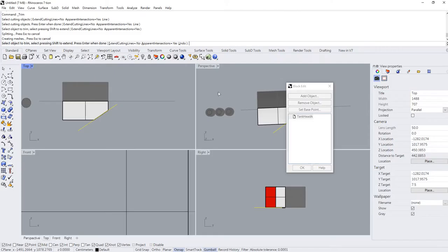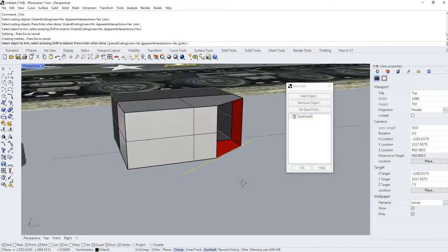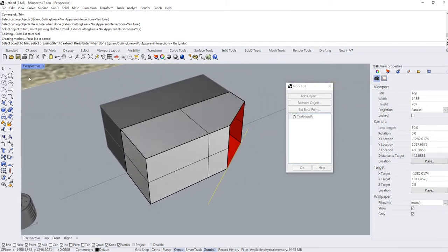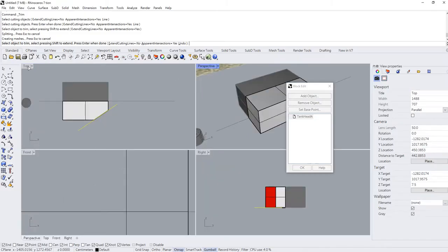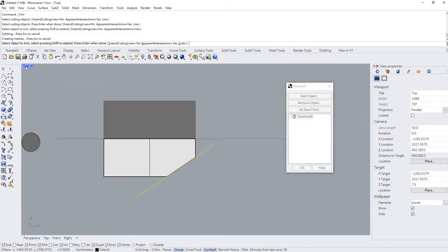If we go to perspective view and you want to cut, basically it is impossible because this is just a simple line and Rhino doesn't know which part you want to cut off. The thing we want to cut off actually is this corner and the cutting section is supposed to be a vertical line. So it's better for you to switch to the top view to do the cutting. So remember, no matter whether you are going to use trim or split, and whether you are using line or surface for cutting, make sure you are under the right perspective, the right view.